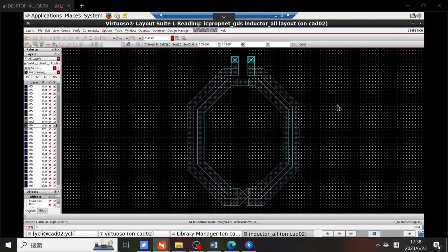The names for the top metal used in different PDKs are normally different, so the GDS file that we provide uses the names of bottom metal layers, which are M1, M2, and M3. After the layout is generated, you can change the metal layer to top thick metal as needed. Here is a demonstration of changing the name of metal layer.